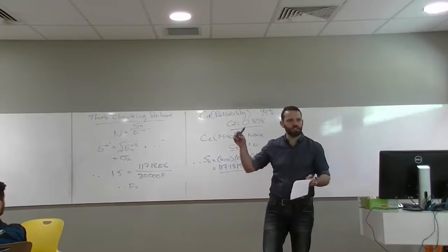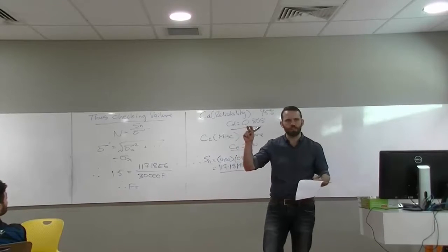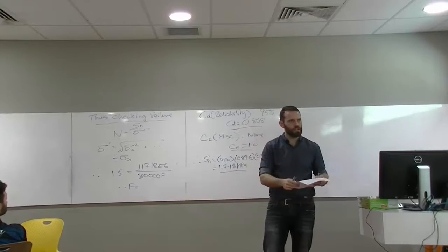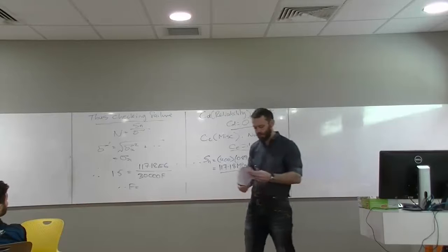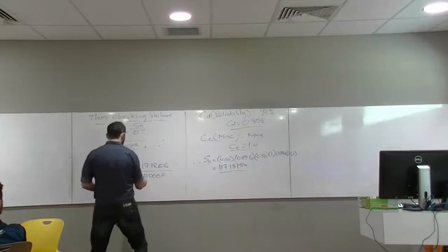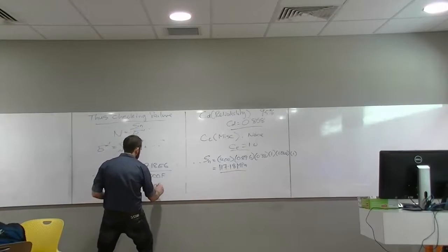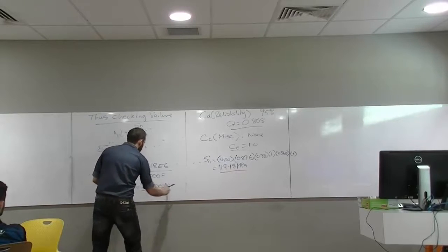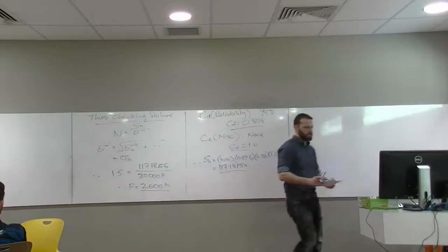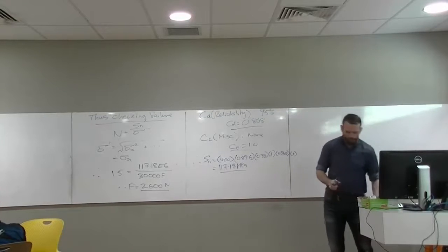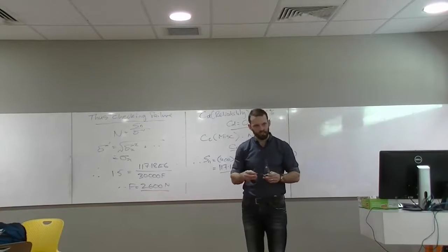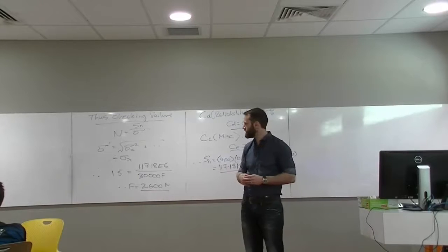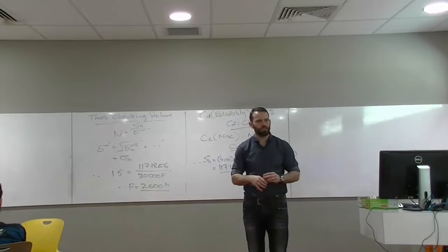All of these factors, some of them will have a little nudge factor. Some people will read one thing, some people will read the other. So, plus or minus maybe 100 newtons or less. Let's say 2,600 newtons or thereabouts. And the last thing we do is recall that that's 2,600 down, 2,600 up, 2,600 down, and over and over again forever, ideally. Cool. Makes sense? Easy enough?